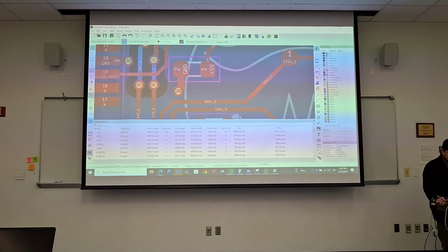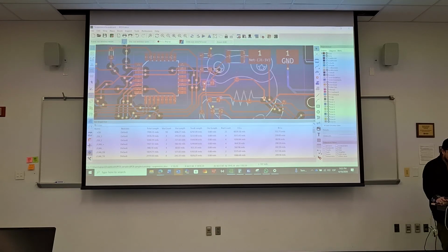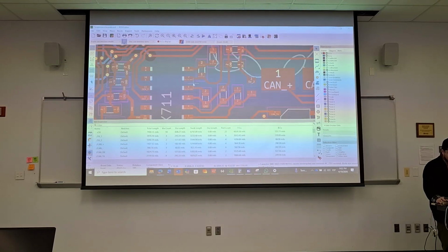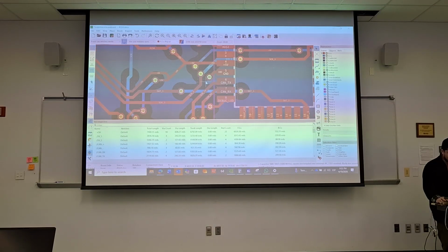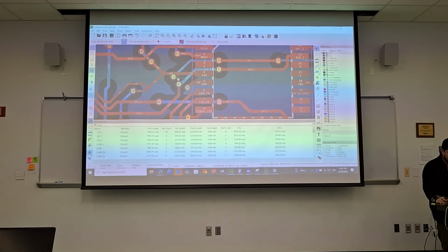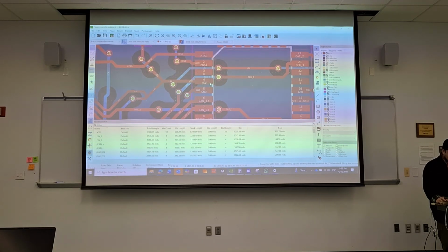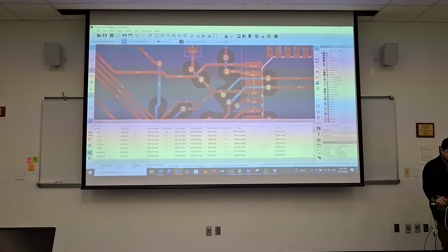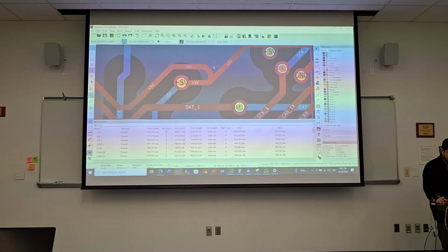Whichever is 5 volts and ground, I would assume that's probably the bypass capacitor. So this is why it's important to look at the schematic, right? So generally on a bunch of these designs, it's good to revisit that, because otherwise these 5 volts, where is it? This 5 volt is only getting it from this via, and this via is not really doing much justice. That's not good.